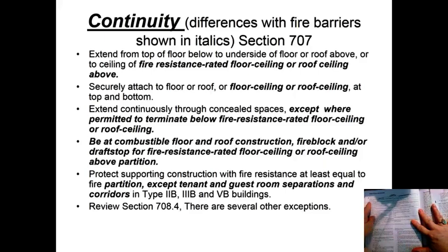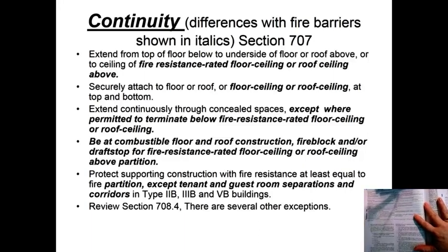You're going to see it says furnace rooms. If you have a furnace room where any piece of equipment has over 400,000 BTUs per hour, it has to have a 1 hour rating or provide an automatic sprinkler system. So we might see paint shops, body shops, laundry rooms, because sometimes you might have hotels that have a laundry room in there. And the laundry room, of course, over 100 square feet, has to have a 1 hour fire rating.